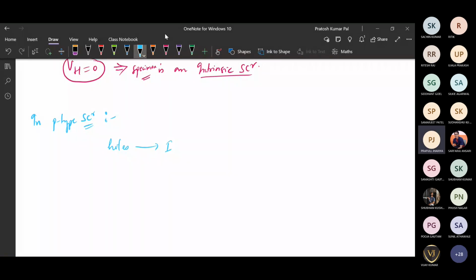So when we are placing these holes into the condition of magnetic field, and here current direction is in positive x direction and magnetic field is in positive z direction, then the force experienced will be such that the holes are forced downside, that means to the surface 1. The holes, being the majority charge carriers, will be forced because of the Hall effect. It will be experiencing a force in negative y direction.